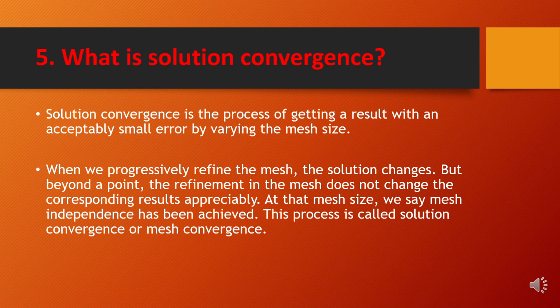Question number 5. What is solution convergence? This is a very important concept that I have seen that many engineers working in the FEA field sometimes don't know. Just because you come up with a random mesh and you solve the analysis does not mean that the solution will be correct. You have to decide the proper mesh size. For that, this solution convergence concept is central.